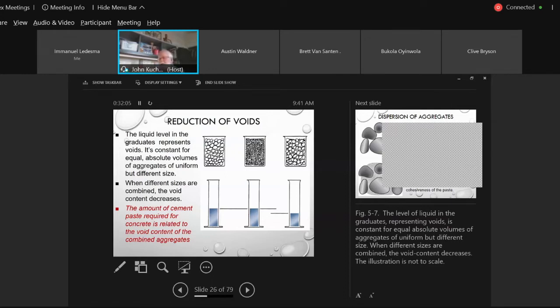That's what's going to give you the strength. If you got pop-outs where you got an intact aggregate on one side of the fracture, and you can see the dimple or the crater where that aggregate was on the other side, it pulled out. Okay? The bond broke. You got weak concrete, especially if there's lots of that aggregate. Good concrete, you're going to get some pop-outs. That goes without saying. So always look at a failure plane. Now, with crushed aggregates that we're using, it's pretty hard to determine unless you quickly look at it right after the test. Did it fracture in the test, or was it fractured from the crushing operation? Okay, so you have to look at it and make some judgments there.